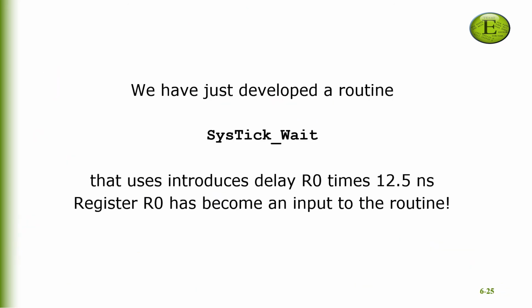Note that we have just developed a routine, SysTick_wait, that introduces a delay of R0 times 12.5 nanoseconds. And in that process, the register R0 has inevitably become an input to this routine.